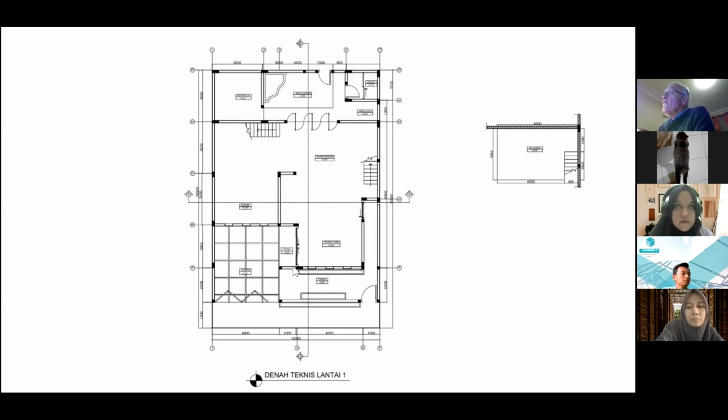And we haven't even got a frame in this direction, because that column is strong in the X direction, but this column is weak. It is weak in the X direction. So we don't really have any seismic resistance in the A grid line. What about B, the B grid line?